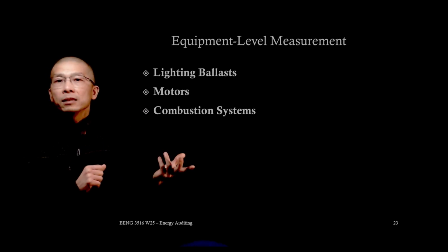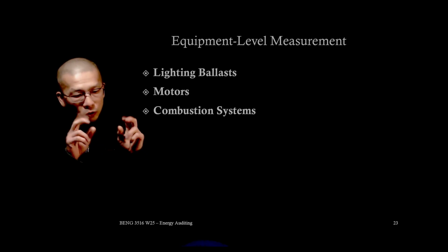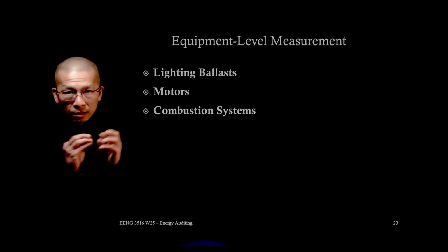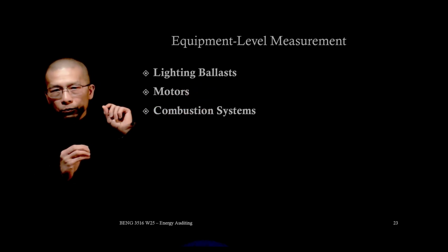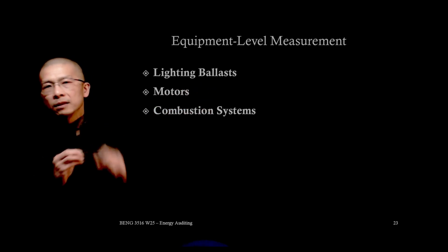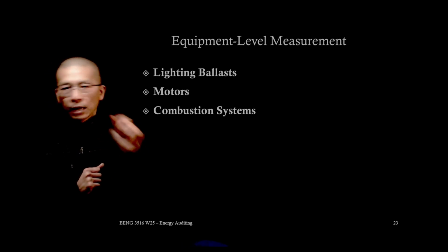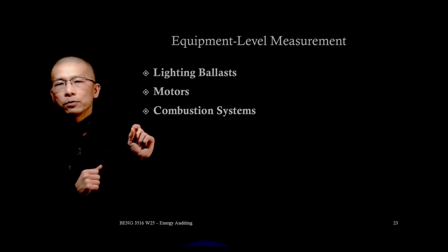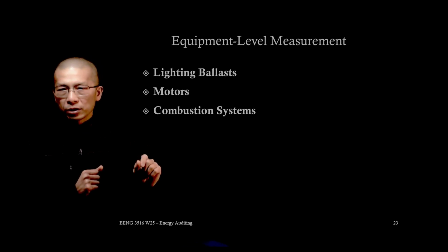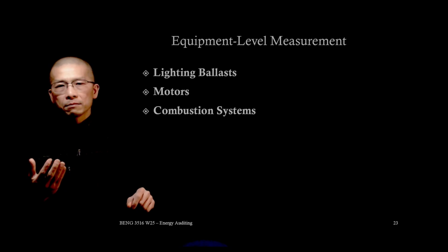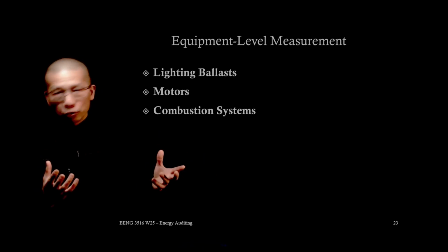For LED, these days we call them drivers, also the control part of the lamp. Say a lighting ballast for compact fluorescent lighting: we measure the electrical input, light output, and use a power meter to determine efficiency, and detect any aging or poorly matched ballast.